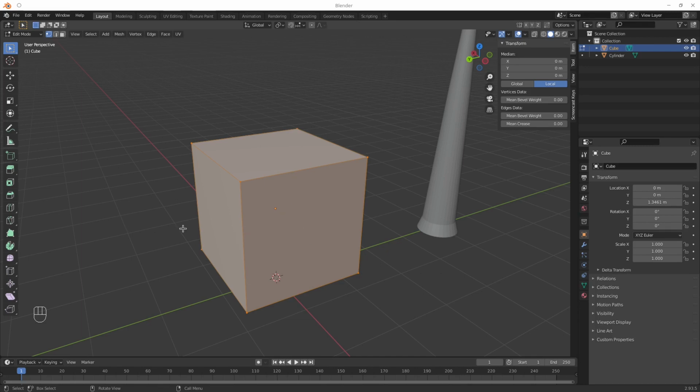And to do that, there's the loop cut tool. So for instance, I can add a loop around this by just pressing Control R. Yeah, there we go. So if you get close to a border, Blender will understand where you want to place your loop cuts.